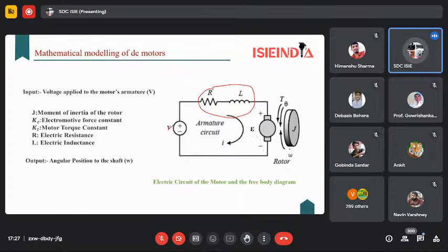The motor will generate a back EMF, which is denoted with epsilon, and the motor is also connected with a shaft for the rotation part, which creates a moment of inertia, identified as J. The rotational speed is omega, and the produced torque is called tau.